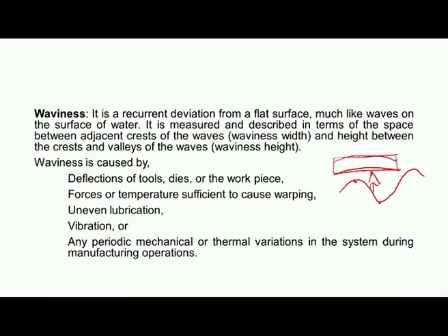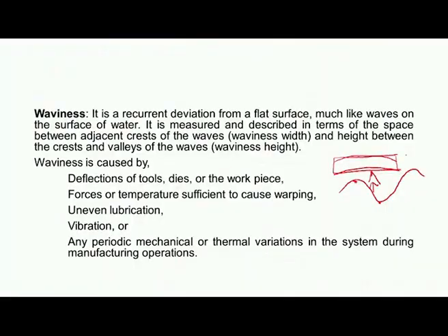Because of this, waviness may occur, and also the cutting forces will cause waviness, and temperature variations cause variations, and if the lubrication is not proper, then also waviness may occur, and machine tool vibration and chatter of the cutting tool. These are some of the reasons why waviness occurs on the surface.